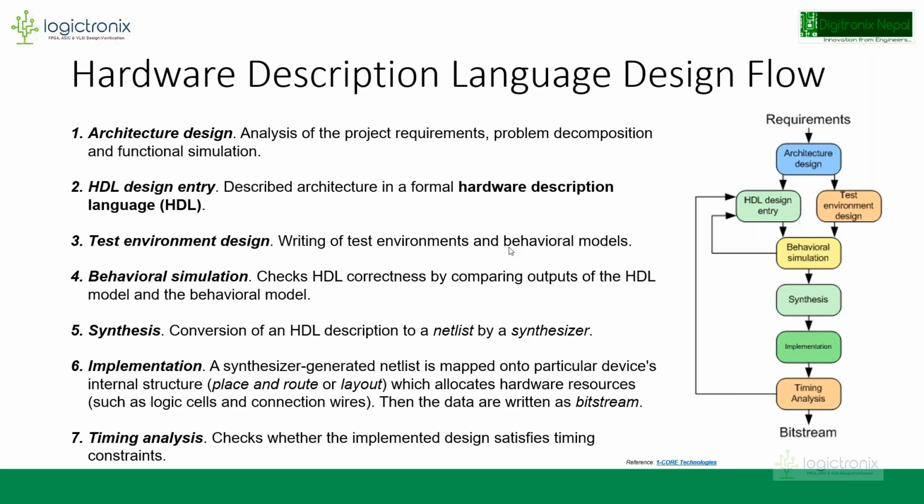It also generates the netlist, or the process will create the RTL schematic also, so we can get the overall netlist, meaning how the logic units will be connected, etc., in the schematic. The next step is the implementation step. In the implementation step, the mapping and the planning process will be done. Basically IO mapping and IO planning will be done in this implementation.